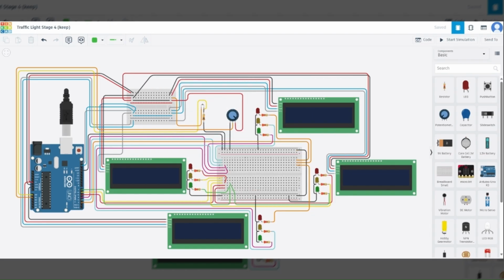We simulate a 4-way intersection with synchronized traffic lights and pedestrian LCD signs. North-south and east-west traffic lights operate on opposite schedules. Each direction has an LCD screen that displays pedestrian messages based on traffic light phase. The LCD screens use I2C communication, connecting to the Arduino via SDA and SCL pins. Each LCD also requires power and ground.